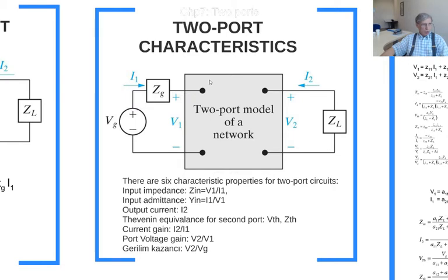Because you are doing the same job by using less electrical power, so that's quite reasonable. So in order to calculate that power, you need that impedance higher, isn't it? If this input impedance is high enough, you're going to say that the power consumption is going to be less.